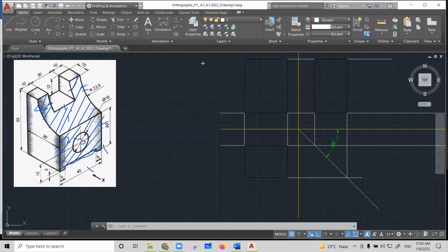So if it is visible to you, then you go to line, take one point at the corner, means in AutoCAD, and with manual drawing, you just go to this point. From here, you take 5 millimeter, then you go 3 millimeter. Then the total length is 50. So at the end, these steps are of 5 millimeter length, so the remaining will be 30 millimeter.